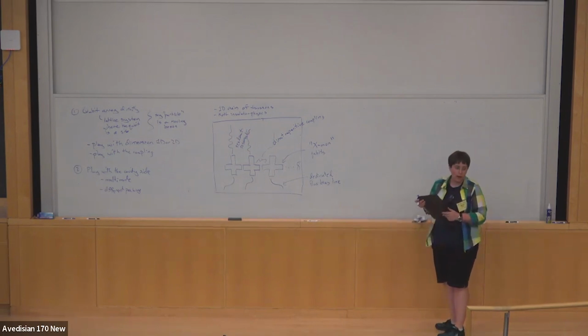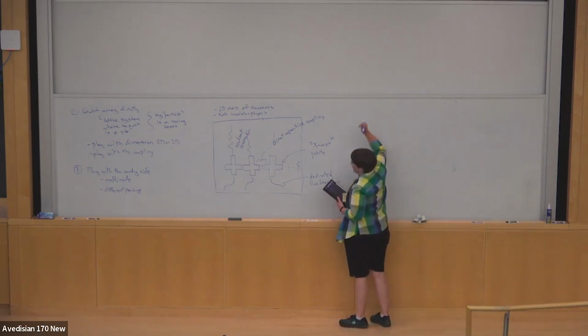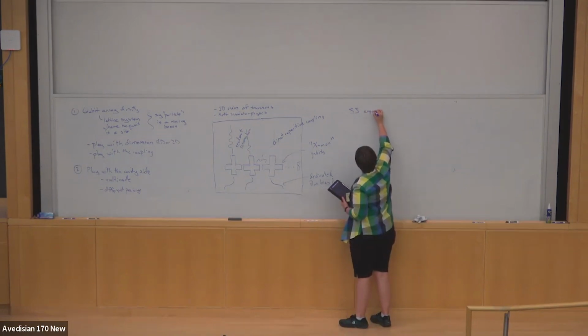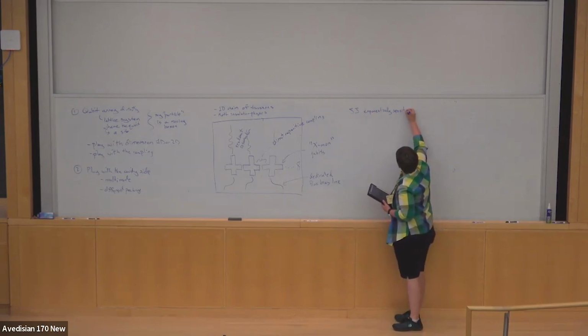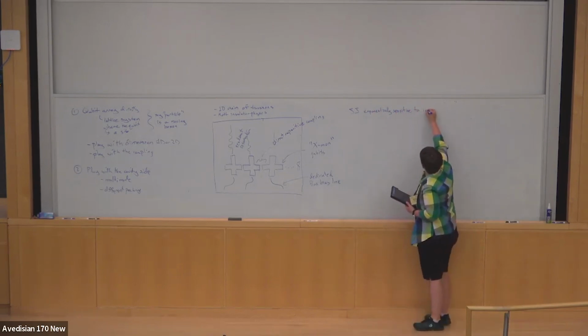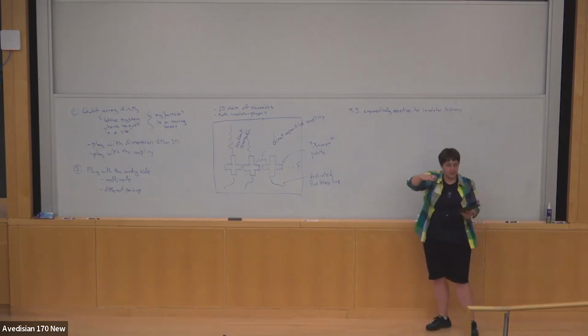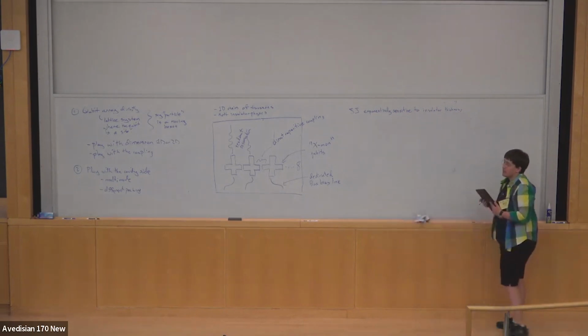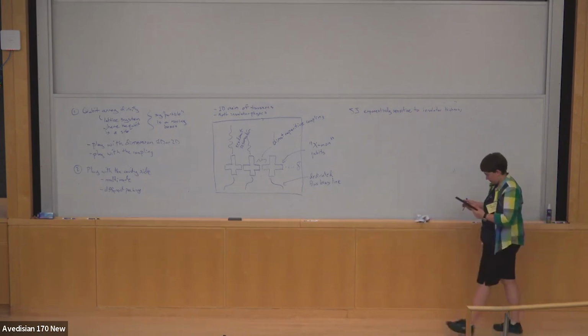So let's talk about why this looks this way, what's cool about it, what's annoying about it. One of the most annoying things in superconducting circuits is that Josephson junctions are exponentially sensitive to the insulator thickness. You make a superconductor, a layer of insulator, and the next superconductor, and your EJ depends exponentially on the thickness of that insulating layer.